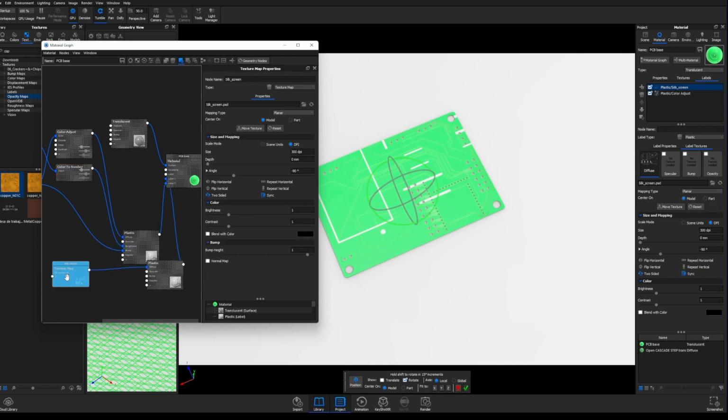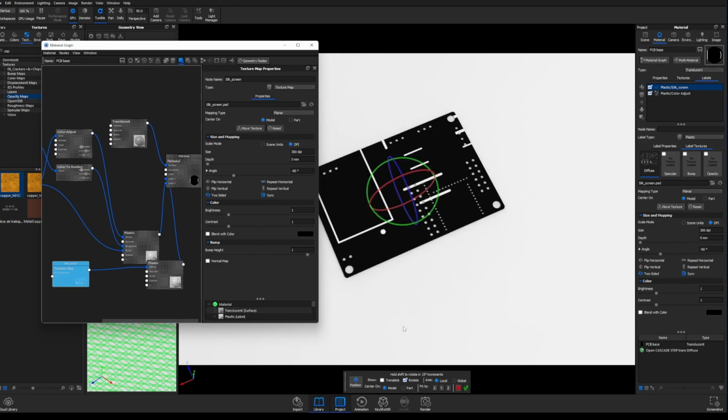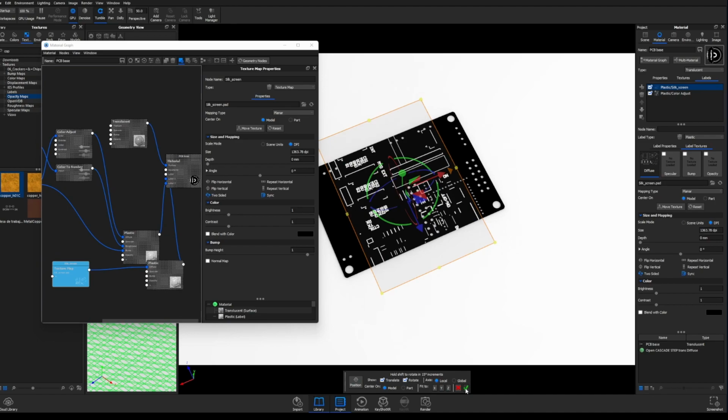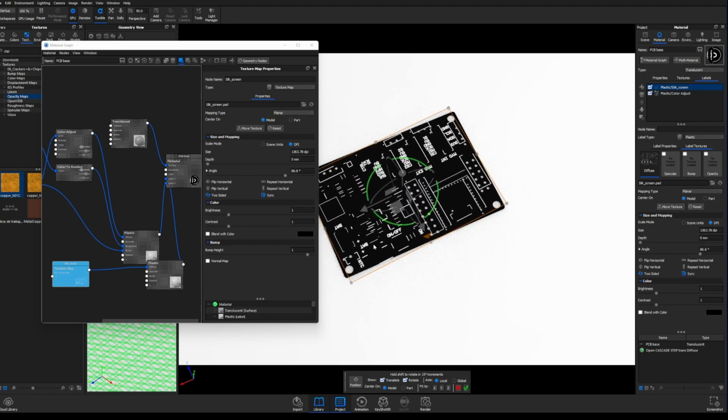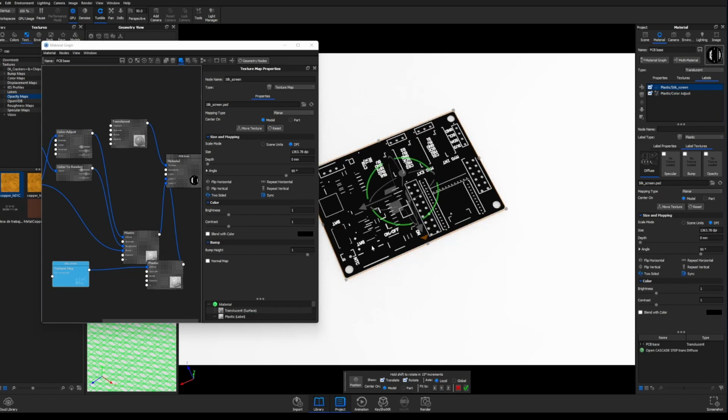So I'm gonna click C again to isolate this. We already know that we can use fit to this plane. We have to rotate it. Hold shift to lock the rotation into 15 degrees position. So this is 90 degrees rotation. I'm gonna click accept.